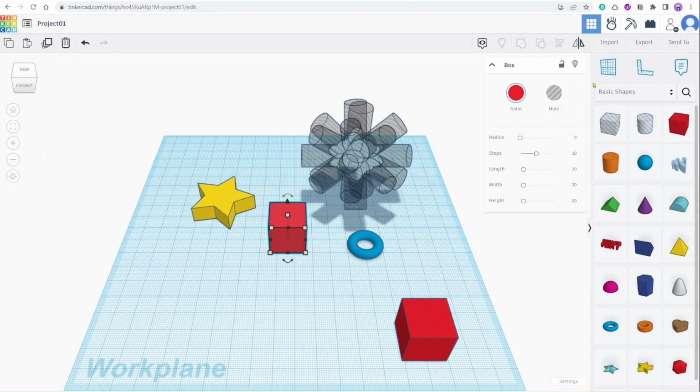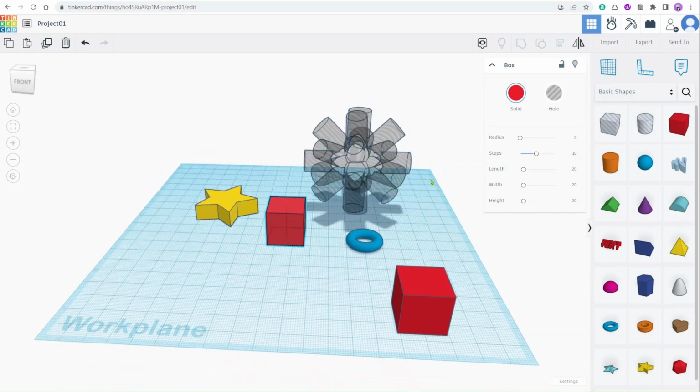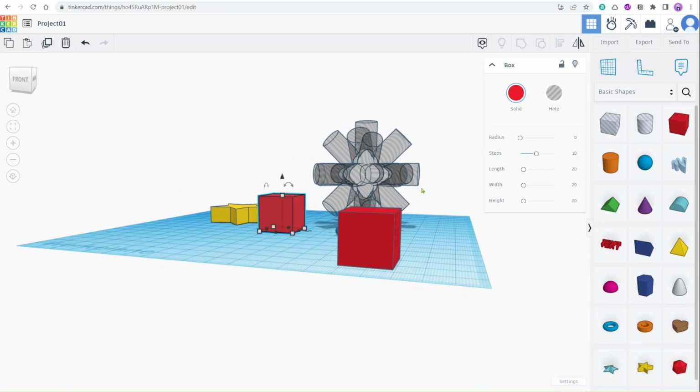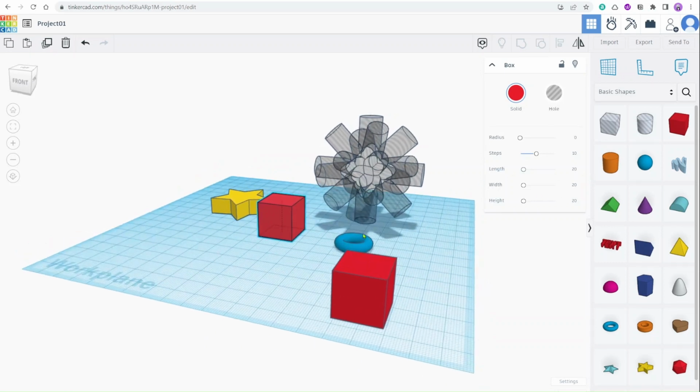And let's talk about these two. This one is the Workplane tool, and the shortcut key for this function is W. Either click on this or just press W. All right. Let me bring in a scenario. The scenario is to stack another object on top of this cube object, right?